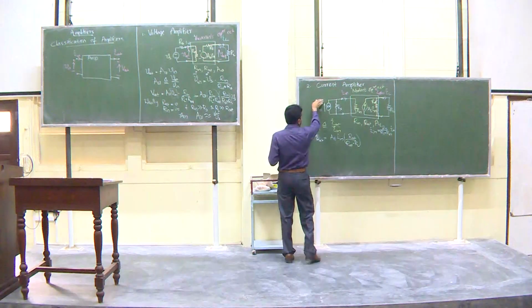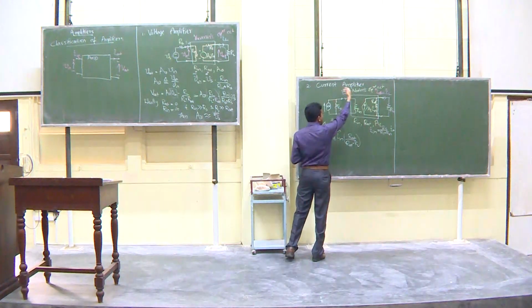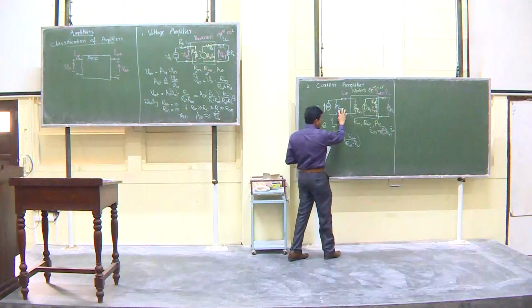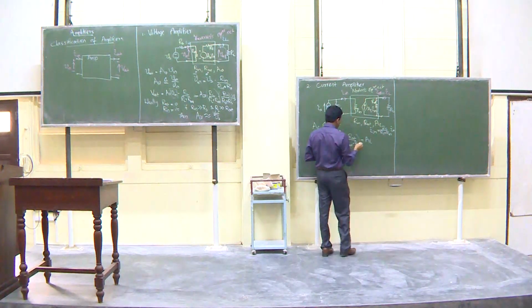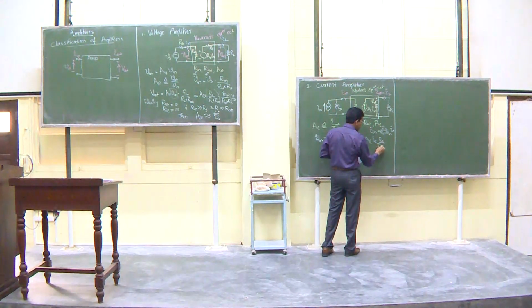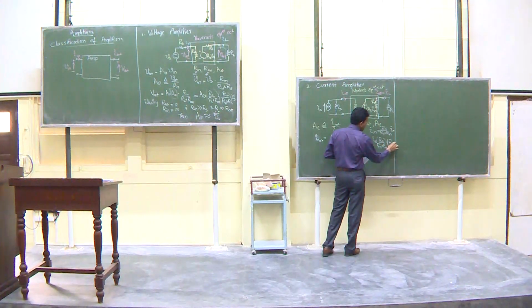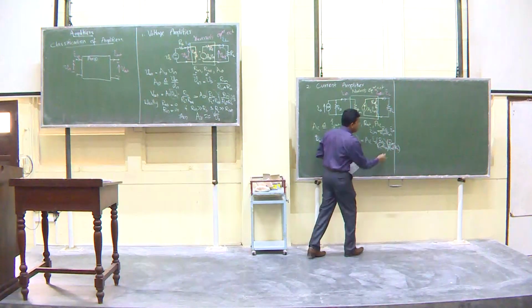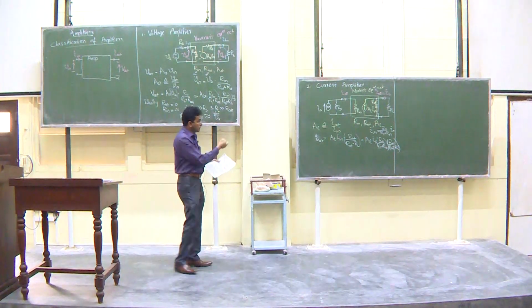Similar argument, Is comes and divides into 2. The larger resistor gets the smaller portion, the smaller one gets the larger portion. So, therefore, you need to interchange these values. So, you can also write this as AI Is times Rs over Rs plus R in times R out over R out plus R L. So, that is the output relationship. So, that is the output current.